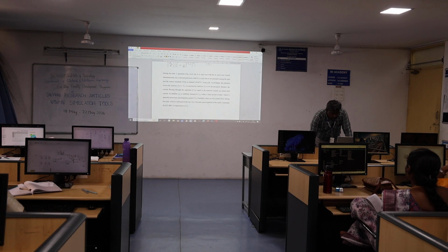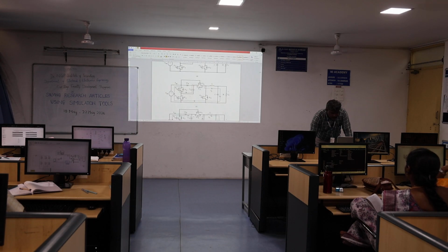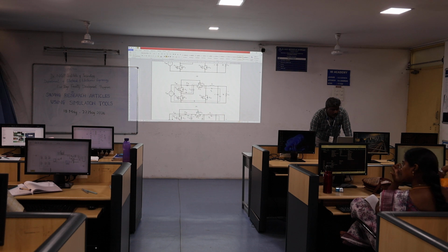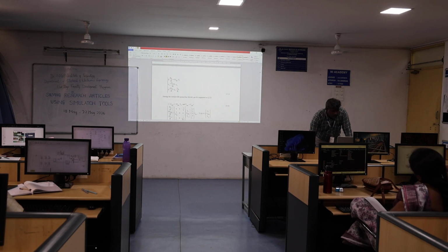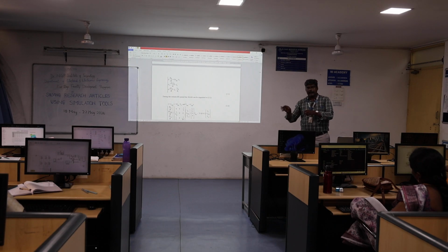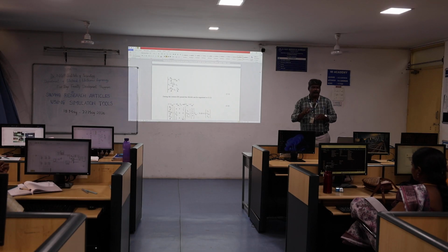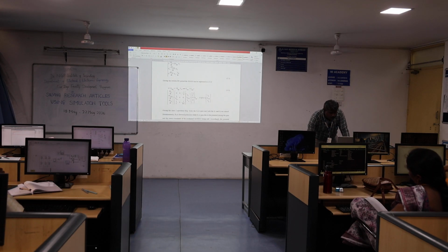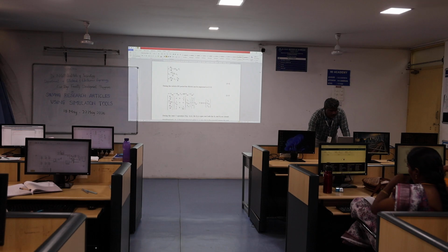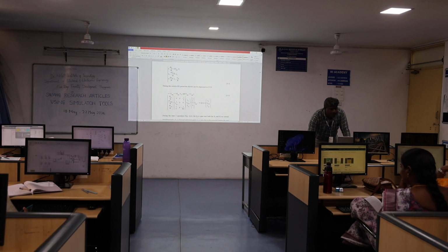Next, another variable is CB. So now go to the circuit. In the circuit, what is the current flowing through the capacitor CB? It is also equal to the inductor current. So the current through the capacitor formula: CB into dVC by dt is equal to IL. So now we form the next equation, the current equation. This is the way we write down the differential equation or state equation during the on time of the switch. During the on time of the converter, apply KVL and KCL, then you can form the equations. Next, we have three storage elements, so we assigned three state variables. Now we formed three equations.